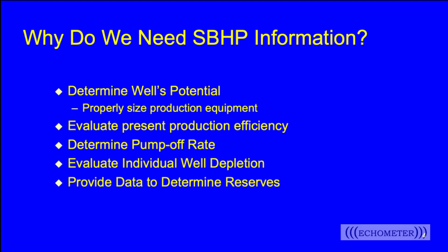We'll also get the depletion off of this. We'll see how much the reservoir pressure or the static bottom hole pressure is changing with time. And I use the words static bottom hole pressure and reservoir pressure interchangeably. Even if we acquire static bottom hole pressure on several wells throughout a field or a lease, we can compare that to see how the depletion is changing throughout the lease. This also provides data that we might use to calculate the reserves remaining in the field.